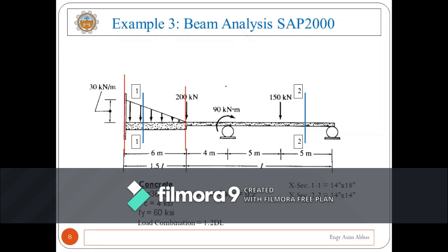We require a grid line at this location because there is a support condition as well as a bending moment applied. Again, we require a grid line at this location, and finally at this location. How many grid lines do we have? 1, 2, 3, 4, and 5. So we require 5 grid lines in X direction.